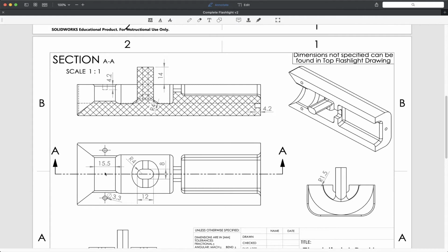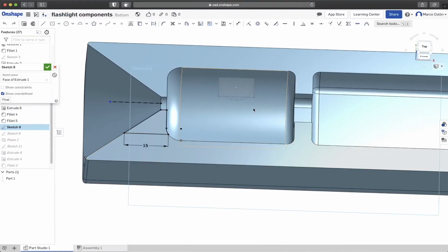So we make this component slightly bigger because we would rather have this hole be slightly bigger than smaller, because if it's smaller, that means these flat sides won't fit flush. And so that's the only reason why we make it slightly bigger, just to account for the errors of the 3D printer. So if we're back here, just double click that, make 15.5.